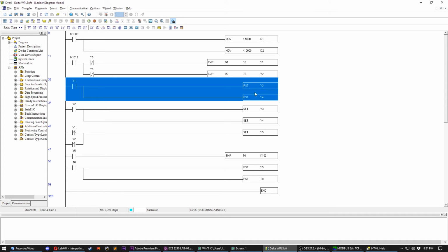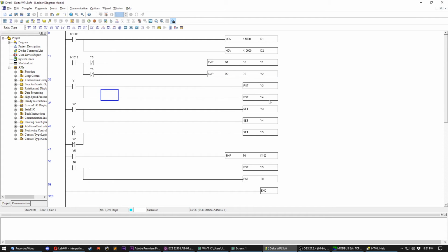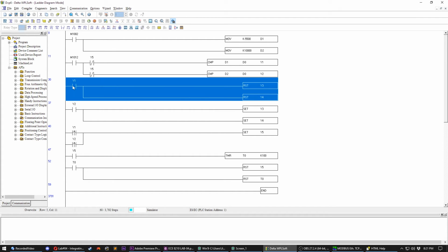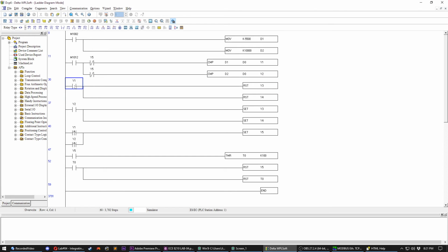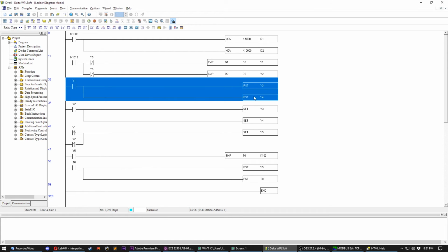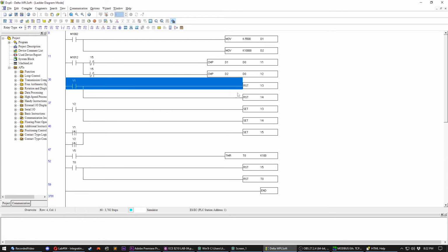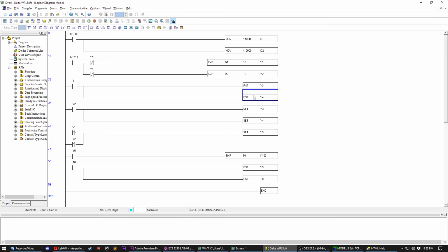So those are set to 0, which means they're turned off, which is simple and fine, but there's a possible situation with this system where if the water level is near its maximum or above its maximum and someone is also using the water, you could have a situation where the water level is fluctuating between the upper bound and just below it. And that's bad for the equipment, and it's just not very good control to have things switching on and off constantly like that.